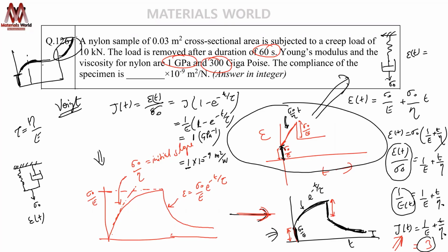And this region we don't get, because at constant load, when we do a creep experiment, we never get this rupture zone. Instead, we get continuous constant secondary creep. It will take years to reach the tertiary or rupture state if your load is constant at room temperature. At high temperature, your creep time will be reduced. That is how the time-temperature superposition principle has come. Anyway, that is what we want to estimate.